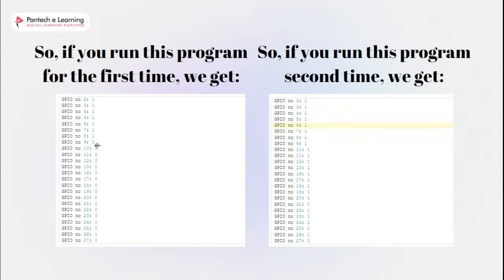From 9 to 27 it will be low, or 0 volt. One thing we do at the end of the program is to call the GPIO cleanup function. This function will reset the mode of all the pins to input, to avoid leaving some pins as output, which can be dangerous for the Pi. It will also alter the future state, meaning the GPIOs in input mode will no longer be at their default.